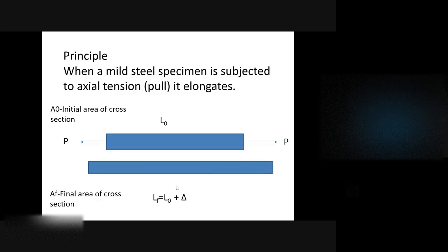Then in addition to that, we are using steel as reinforcement in cement concrete. If we are thinking of a beam, when it is subjected to lateral loads, it will be transverse loading, and it will be bending. So the bottom is subjected to tension and the top undergoes compression. For taking the tension, we are using these steel rods. In that way also, the determination of tensile strength is important.